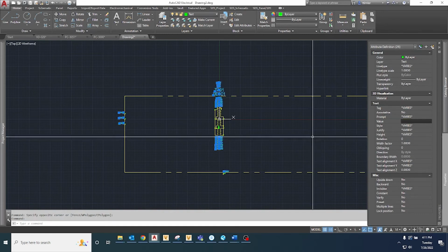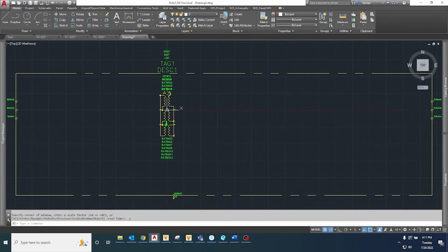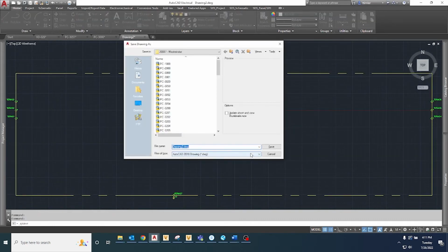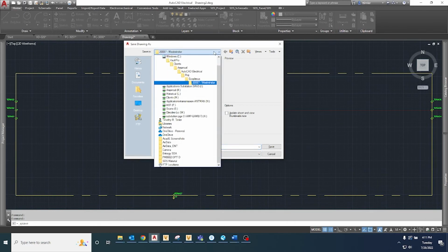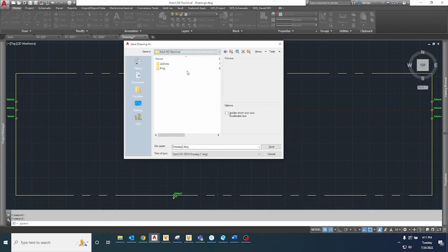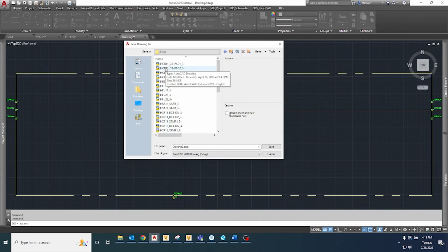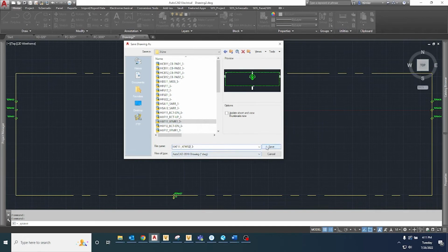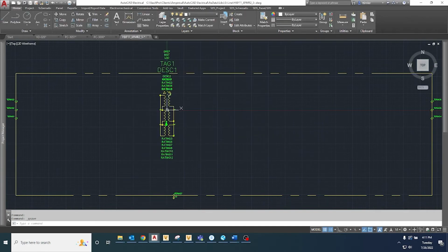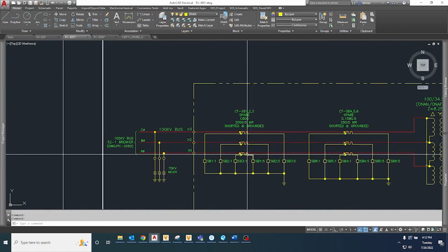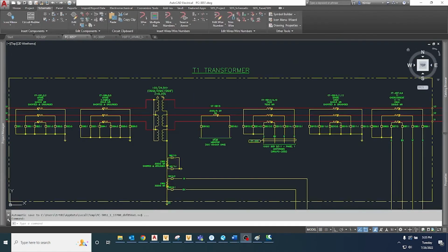Now I'll save the drawing. The symbol has a horizontal orientation, and it's a parent symbol, and it's part of the transformer family. So the symbol name is going to be H for horizontal orientation, XF for the family code, and 1 for the parent symbol. The extra 1, the 5th character, is something we always add to create a toggle function just in case we want to create a flipped version of this symbol. And I gave it transformer 2 as a unique identifier.